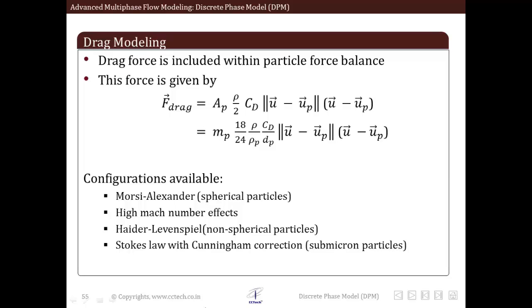Let us quickly review the drag modeling in particle models. Drag force is included within the particle force balance. The force is given by this particular equation. These configurations are available: the Morsi-Alexander, the high Mach number effects, the Haider-Levenspiel for non-spherical particles, and the Stokes law with Cunningham correction, which is for submicron particles.